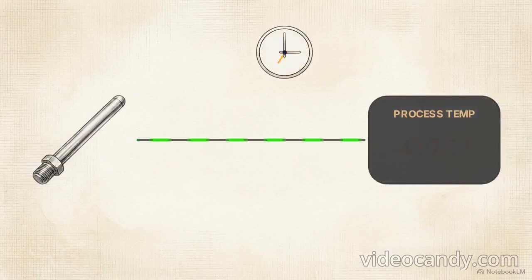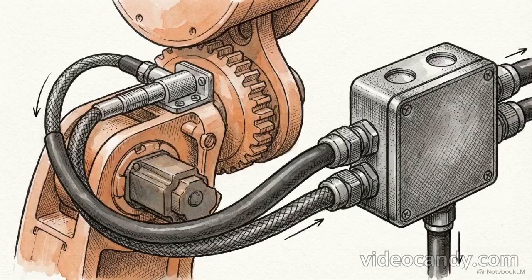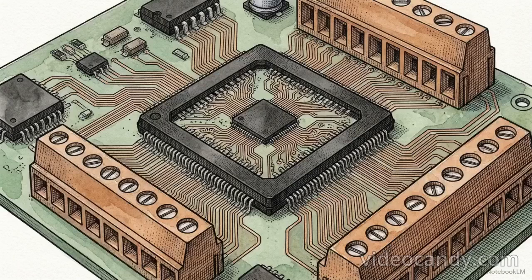Beyond survival, the sensor must deliver data rapidly. Modern control hardware relies on high-speed sampling times, frequently pulling measurements every 100 milliseconds to maintain a tight, continuous stream of data. That high-speed, high-accuracy measurement is the absolute foundation of the control loop. The mathematics of the logic stage rely entirely on the integrity of the data it receives.